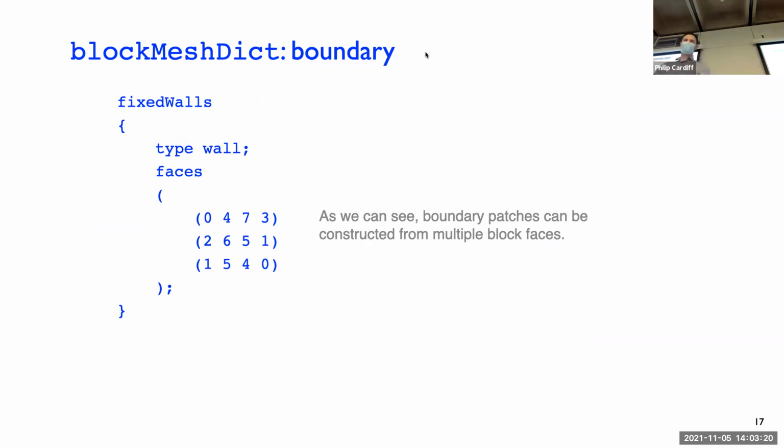Okay, so today I'm just going to finish going through the slides on meshing with OpenFOAM. In the last lecture, we just went through this blockMesh utility. If you've done the lab or started the lab for this week, you would have got a bit more familiar with what exactly blockMesh is and how it's used. It's a simple mesher for simple style geometries.